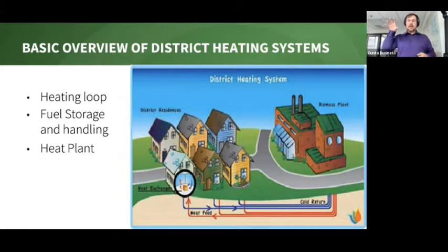So when you create a district heating plant, it's burning wood chips at high efficiency. It's not giving off a lot of particulate, there's no smoke to be noticed, just a little bit of moisture coming out the top, because these things are ultra efficient. Then that heat is passed on to water. The water in the biomass plant has a non-freezing agent, a glycol, and it's sent to the buildings it's heating. In this case it's a bunch of houses, or it could be institutional buildings, including residential buildings. That hot water is circulated through heat exchangers in those buildings, and those buildings are brought up to temperature. They stop requesting heat from the biomass plant, and the pumps turn off in the plant.